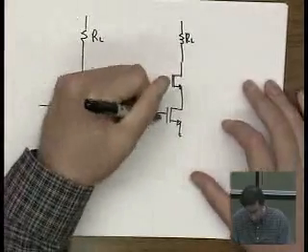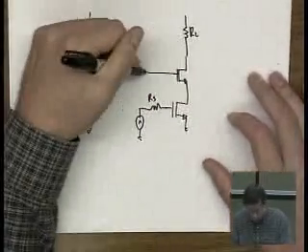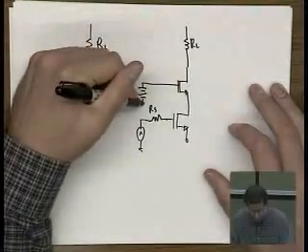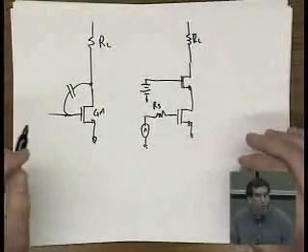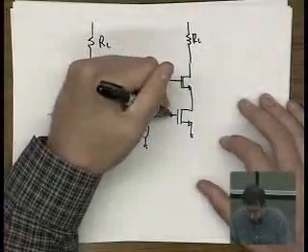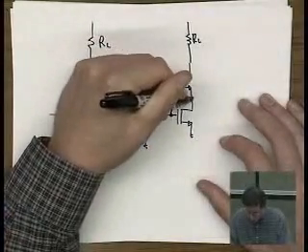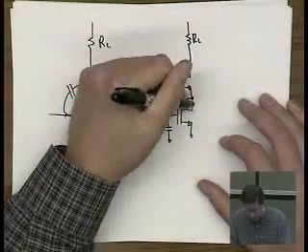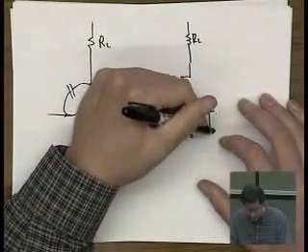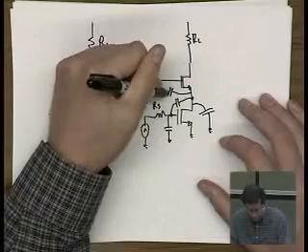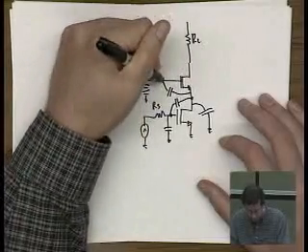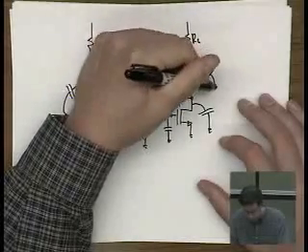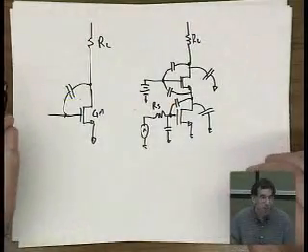And this is what you had to do on your homework. So let's assume that this guy is just tied to some battery, so it's tied to some bias. So now you still have this capacitance going from here to here, right? And so there will still be some Miller effect. Okay, so I've just drawn the primary capacitances.